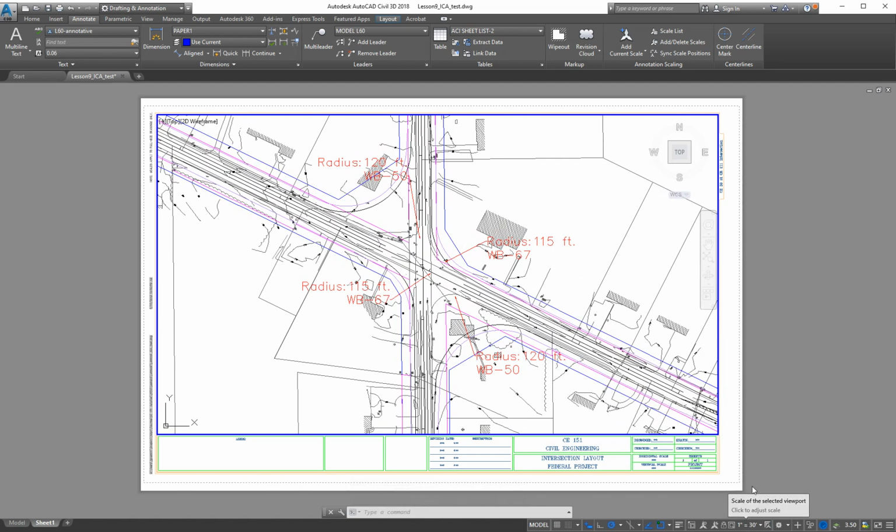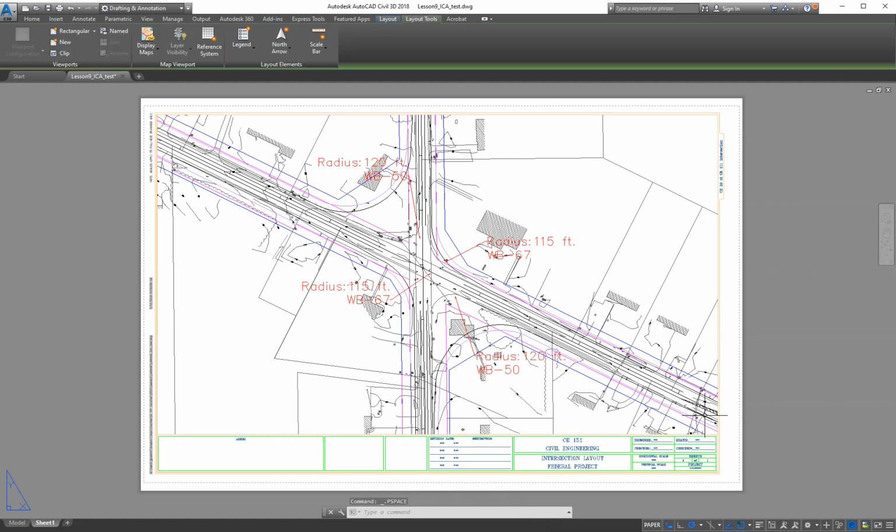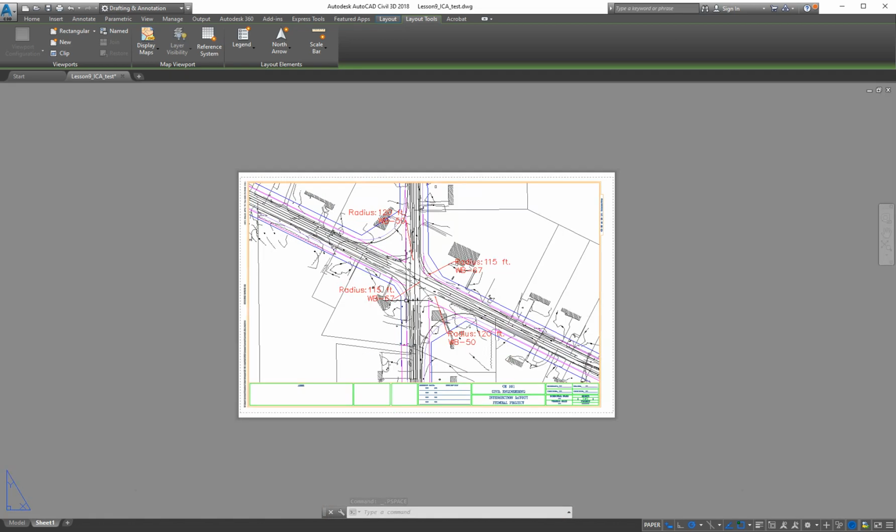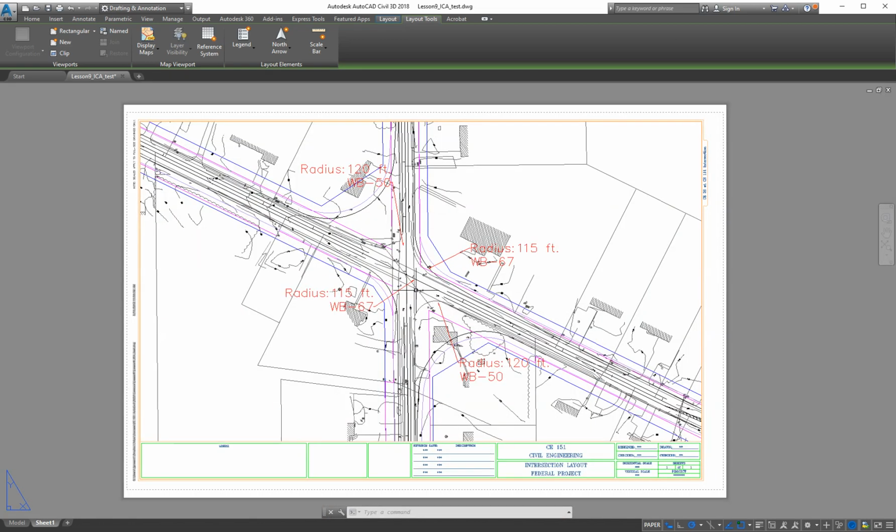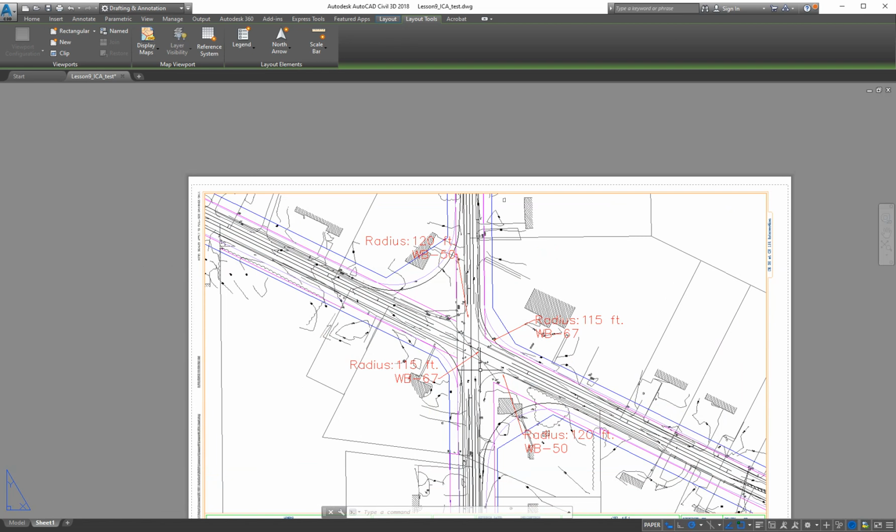Everything looks great, right? And now I'm going to get out of model space, go back to Paperspace, double click. All right, so now the blue border is off. I'm in Paperspace. If I zoom in and out, the whole sheet zooms in and out now. Great, I'm in Paperspace. So that was instruction 4, return to Paperspace.